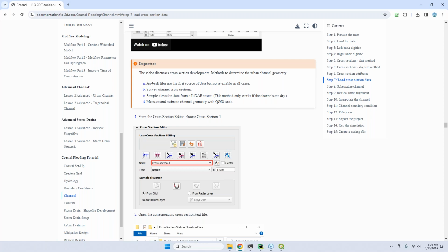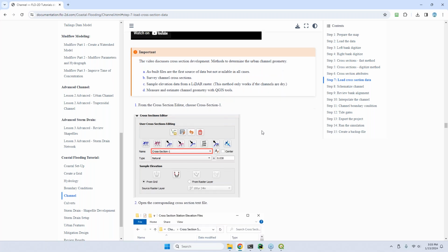They're going to have enough water to help drain systems, but not too deep because of the groundwater. So I'm assuming anywhere from 8 to 12 feet deep might be the depth of this channel. I can use that to help fill in the missing cross-section data using trapezoidal geometry. That's what I did to build these cross sections.